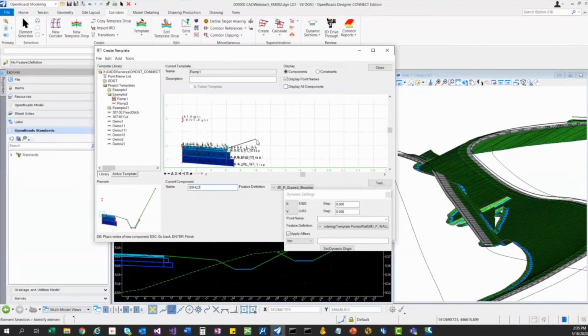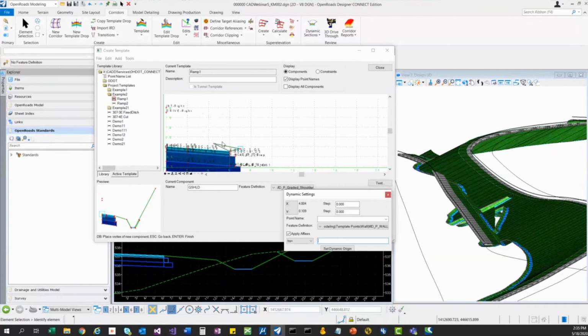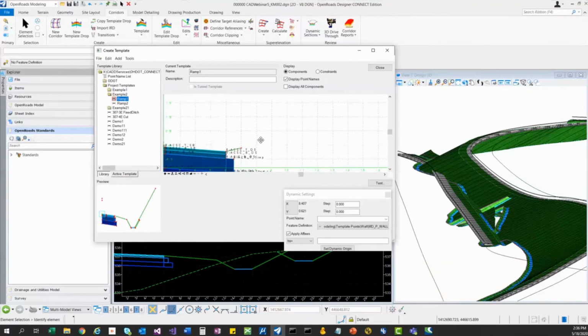Now I'll just place this in, and then I want to use my dynamic settings to place that at a horizontal distance of 1, and maybe I'll just do a 1:8 slope. So there, add that in. I'll make it so it's not a closed shape, and then I'll finish it. I just got a little piece, and then I'm going to build my wall off of this here.